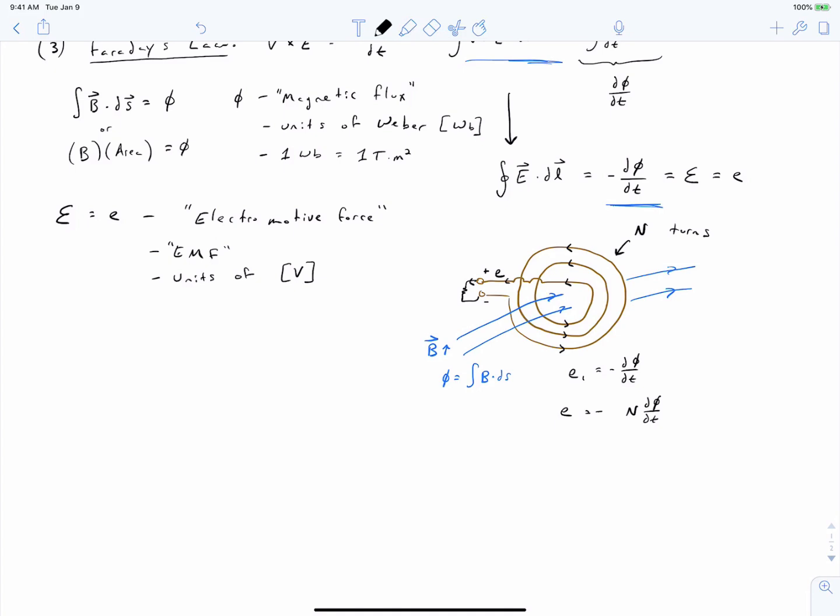So in this class, we'll account for this by introducing something called a winding factor, Kw. Kw is some quantity that's less than 1 that accounts for the fact that not all coils link the same amount of flux. We'll get into defining what we mean exactly by a winding factor later in the course, but I want to introduce the concept now: the winding factor is a means of accounting for a different amount of flux linking each turn of a coil, or if you have many coils in series, a different amount of flux linking each of the coils when you connect them in series.